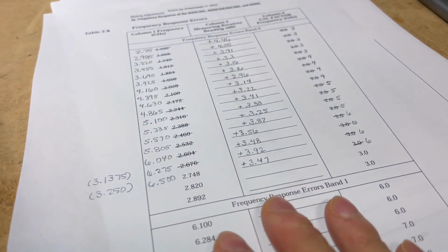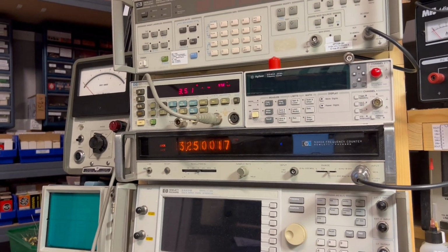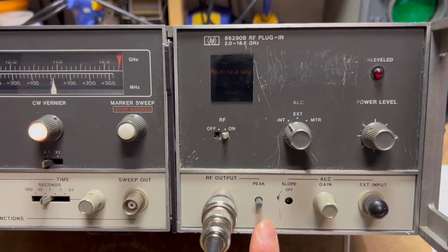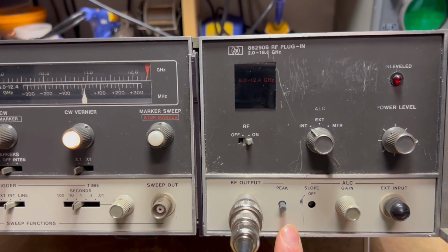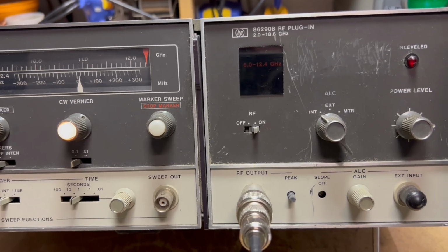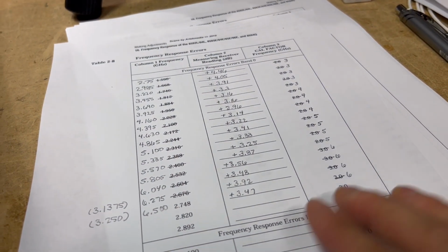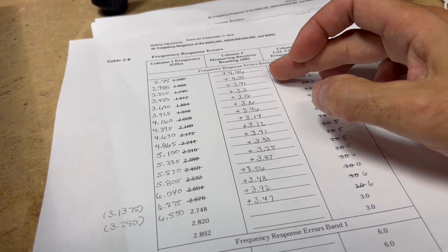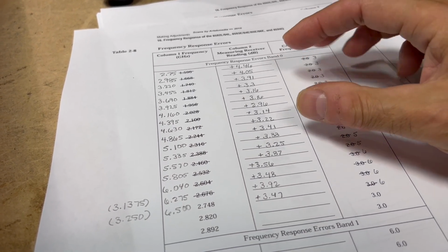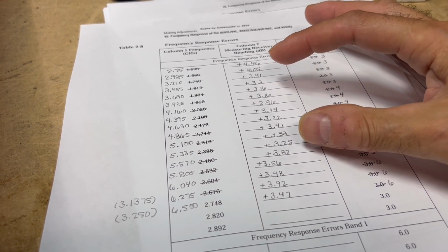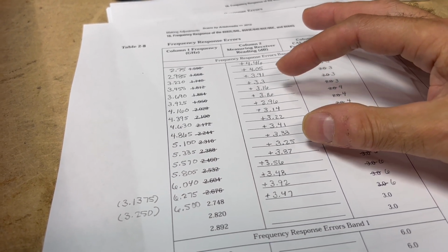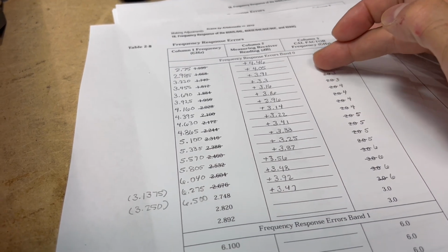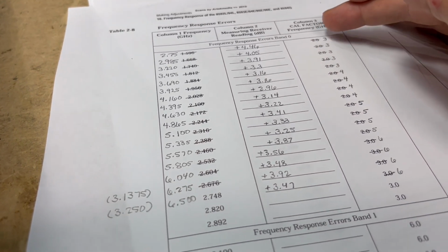I actually recorded on the paper here 3.47, and it sort of fluctuates around there. You can see it's dropped off just a little bit and come back up, and I think that's because this generator is probably not the flattest source, so it tends to fluctuate a little bit. When I take these readings, I had to watch the power meter, see where the fluctuation was, and take a sort of middle value of that fluctuation range, and that's what I have here on the sheet.